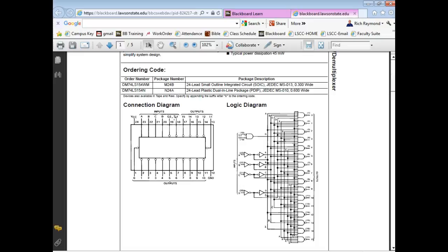They don't have anything hooked up to the input, and I've got it turned all the way down. So this is one way you can check to see if your probe's working. This scope has so much input impedance. Where is this coming from? What frequency is it? 60 cycles. I'm picking up 60 cycles all the time. Normally, to check if a scope probe's working, you put it on and just touch it with your finger.